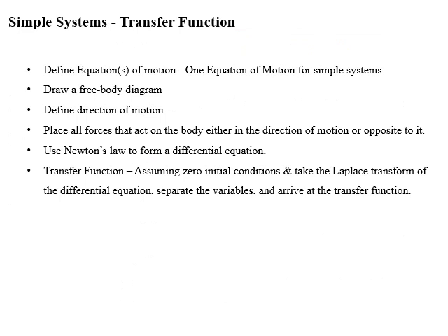Dear students, now we will study simple translational mechanical systems. To find the transfer function of these systems, we have a few rules to be followed. First of all, we have to define equations of motion. In the case of a simple translational mechanical system, one equation is required to define the motion of the system.